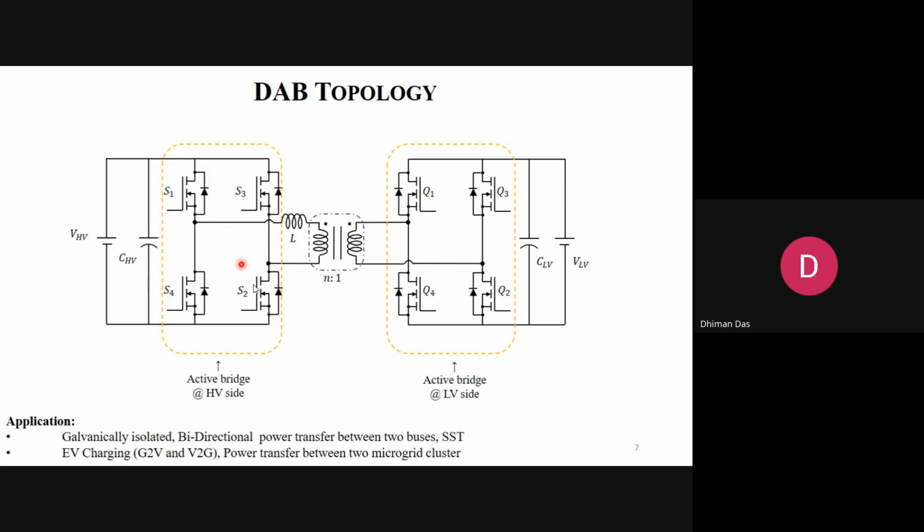It can charge this body capacitance, here also the body capacitance, and the secondary side also, because this inductor will also reflect to the secondary side by a factor of n squared, because this is just a transformer which can translate everything from primary to secondary with a factor. So similarly, at the secondary side, you can also achieve ZVS. So in this converter, every switch can be operated at zero voltage switching, which is called soft switching.